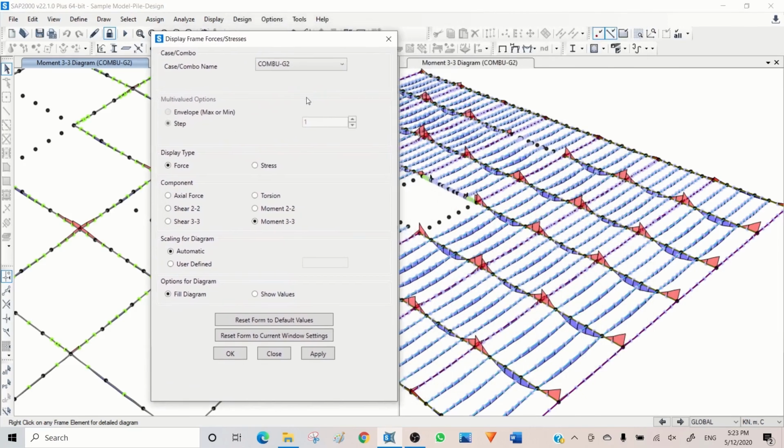Here, because you want to design the beams, you can be very conservative and you can use this low factor to design the beam. So easily you can calculate manually and see what load you are expecting to be transferred here, and for a simple span beam what would be the maximum moment, and then when you have it you can compare here the result.